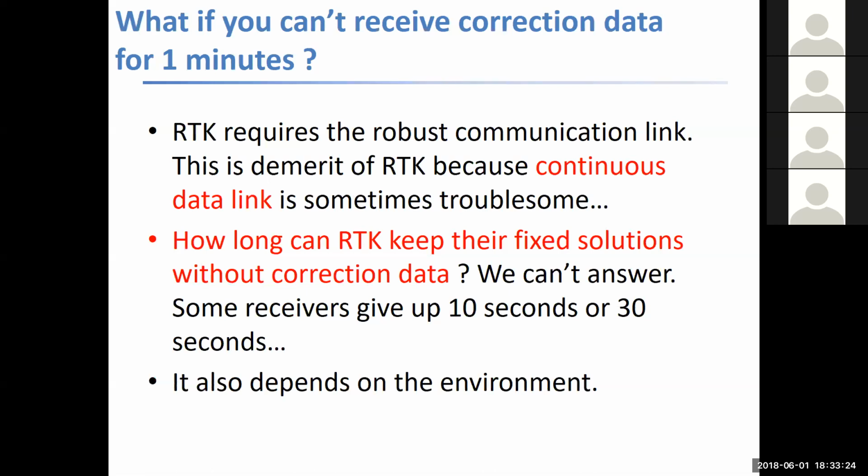Yes, I checked 24 hours real-time RTK just 1 week ago, 24 hours at our campus. Baseline is only 100 meters. And we used a SIM card, smartphone SIM in tethering.